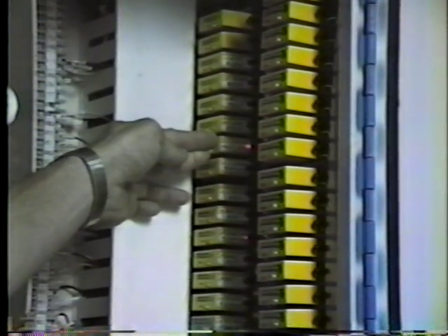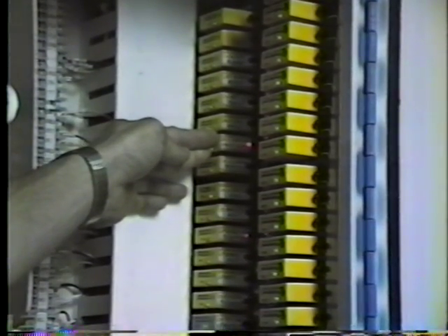What's the one above it? The one above it is the ECC cooling system pressure switch, which is a normally closed switch. When we have pressure, this switch opens. If not, we fire an alarm and shut down the entire system. You would not have any water flow to your clutch.